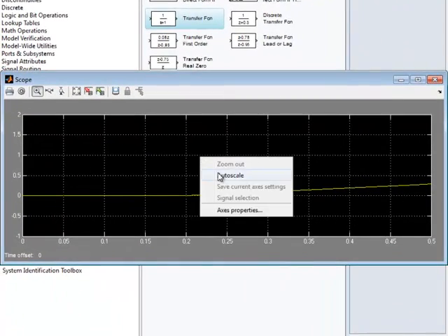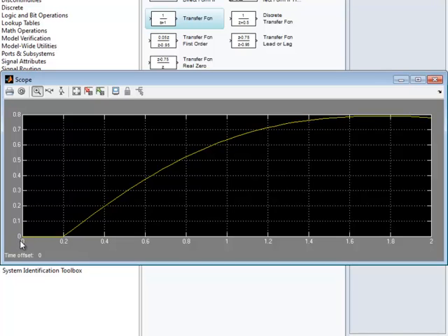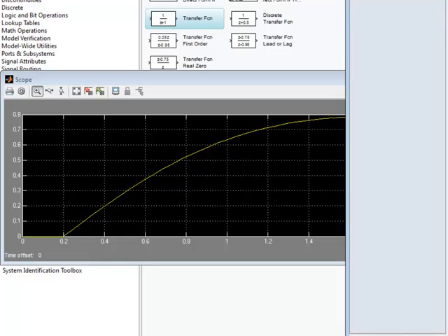And let's change this to 2 seconds for now, and let's run it, and then you just do the step. Let's do the auto scale, and then you see the 0.2 is actually coming from the 0.2 time that we set for the step function, and then this is the behavior of the system to the step input, as you can see at 2 seconds.